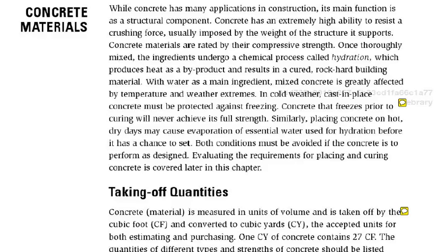One thing you have to remember with concrete is that the basic process that turns cement and stone and sand and water into concrete is hydration, and you need water to hydrate. You need liquid water to hydrate. And that's where weather comes in. Extremes in weather that affect the water, affect the hydration, and so affect the strength of the concrete. You have to be careful that you don't do work in cold weather, especially freezing.